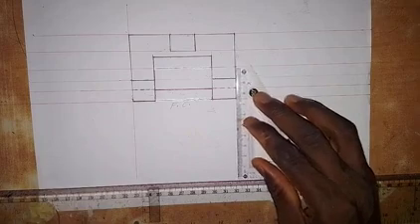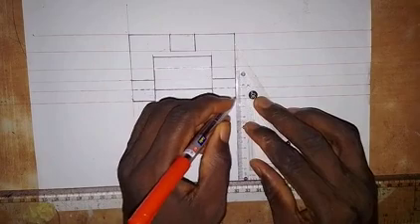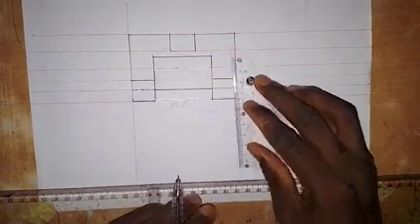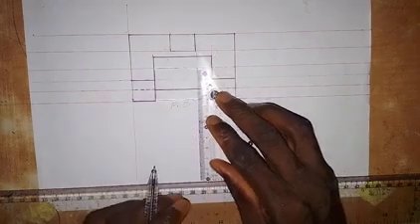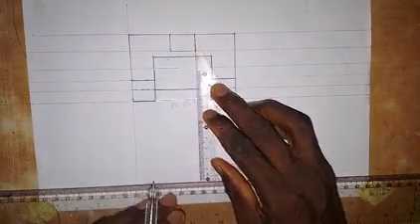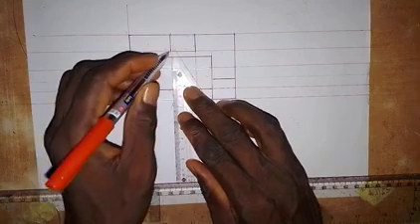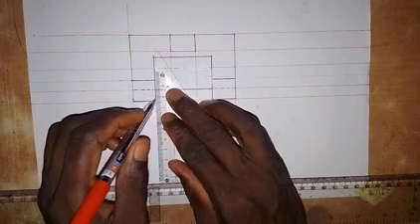Those are things that we are going to put together to get the plan or the top view of this object. First of all, we need to draw a vertical line. We draw a vertical line from this point, and also from this point. I also need to come here and draw this line down like this, and from this point I will draw a vertical line down. Then from this point I will take a vertical line down.